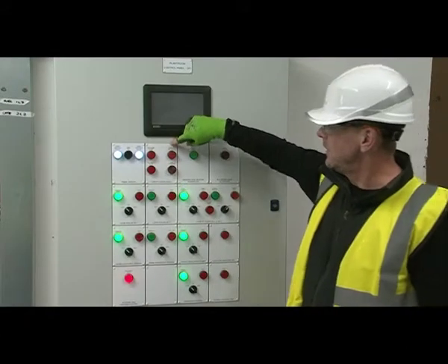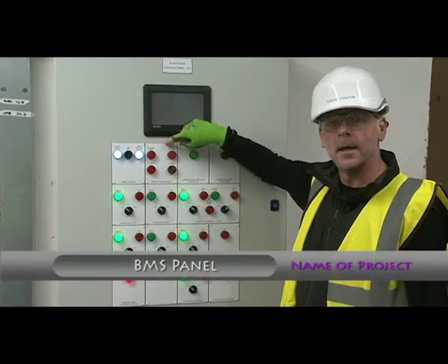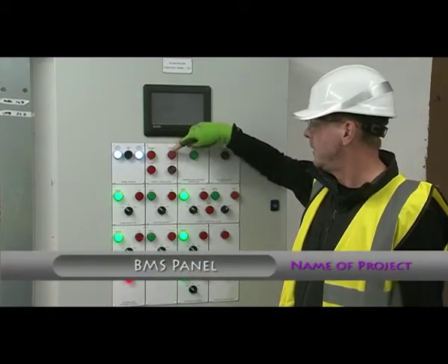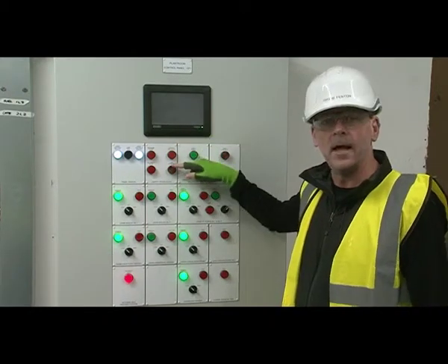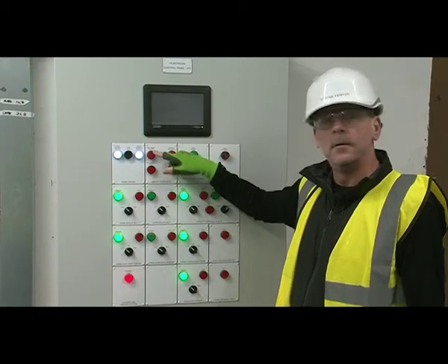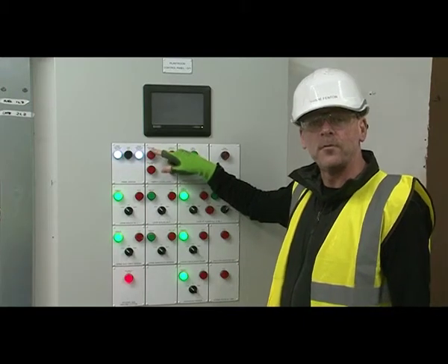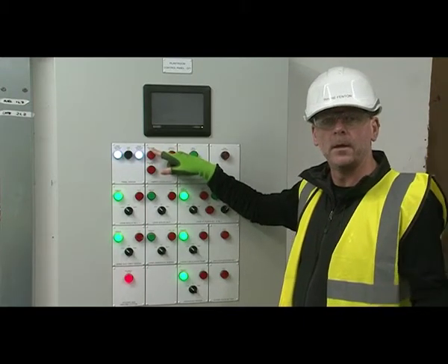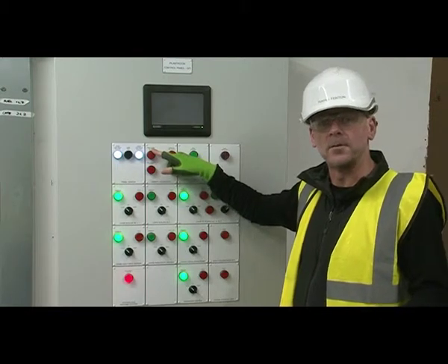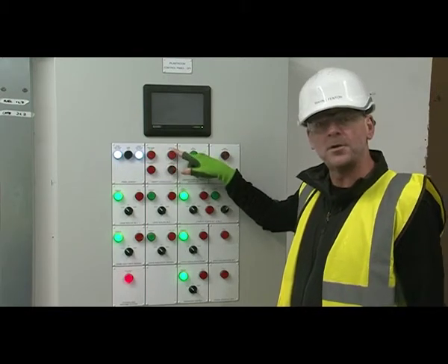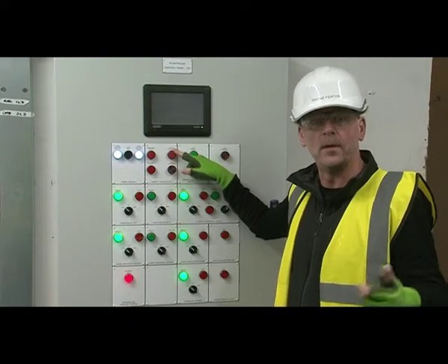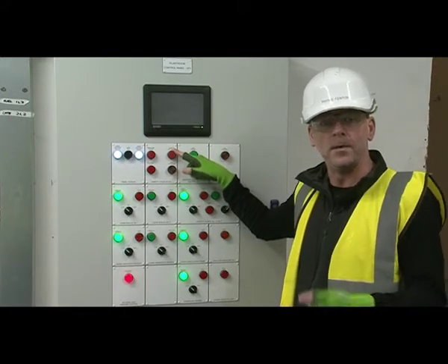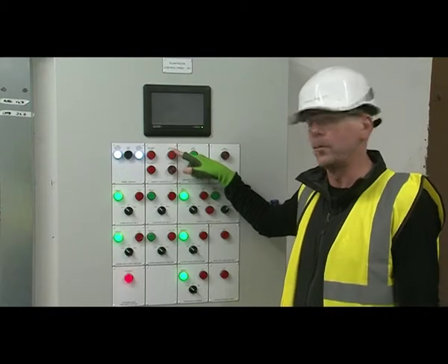The next section is our safety interlocks, and here we have a fire alarm active, PX unit fault, gas safety active, and a gas detected. Self-explanatory, but the fire alarm goes off, it will shut down all gas plant and ventilation plant. Pressurisation unit fault goes, that will shut down all wet plant, which is boilers and pumps, and you'll have to investigate the reason for these faults.